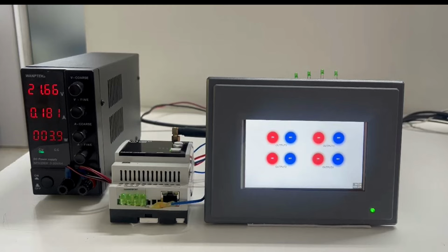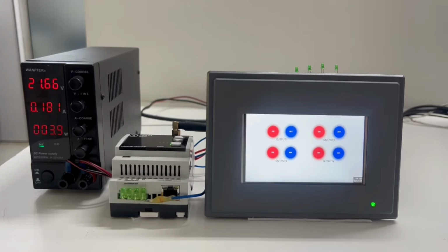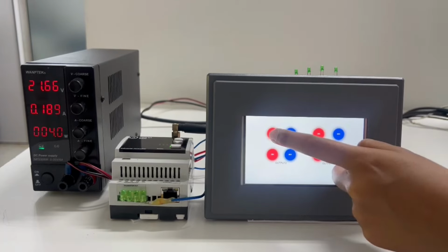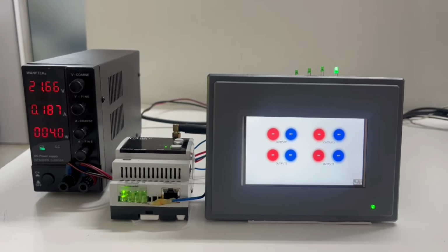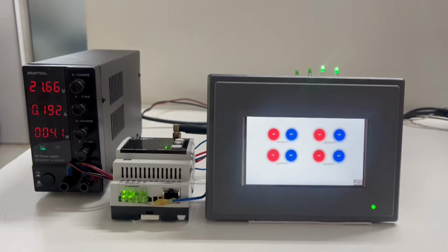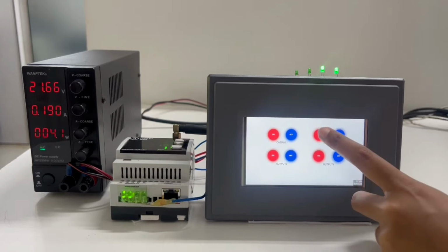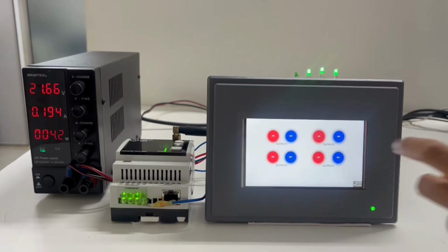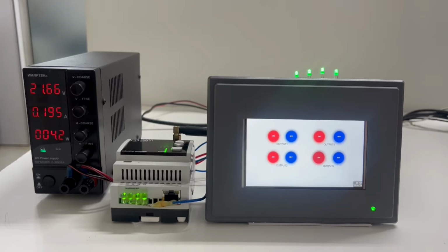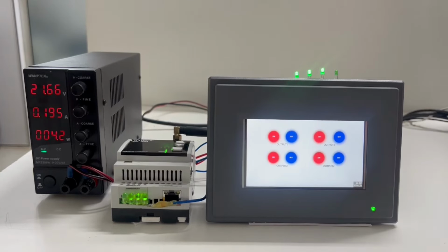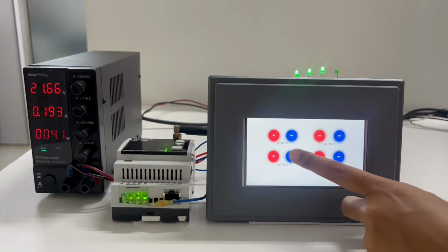This video tutorial shows you how to use the Modbus protocol with NORVI ESP32 HMI. We use NORVI ESP32 HMI as a Modbus master and NORVI GSM A08TL device as a Modbus slave. Here, we show how to program the NORVI HMI as a Modbus master and turn on the transistor outputs of the Modbus slave. In technical terms, writing two coil registers on a Modbus slave.